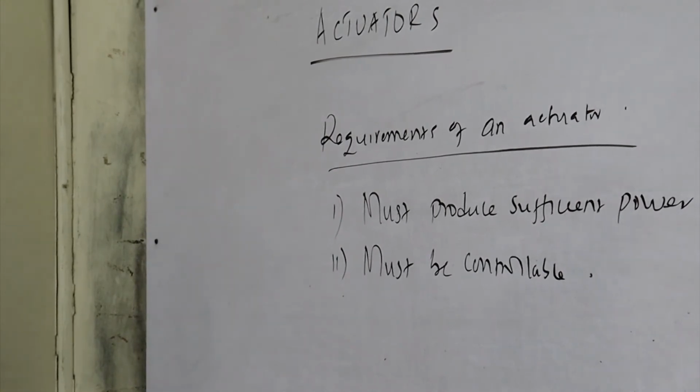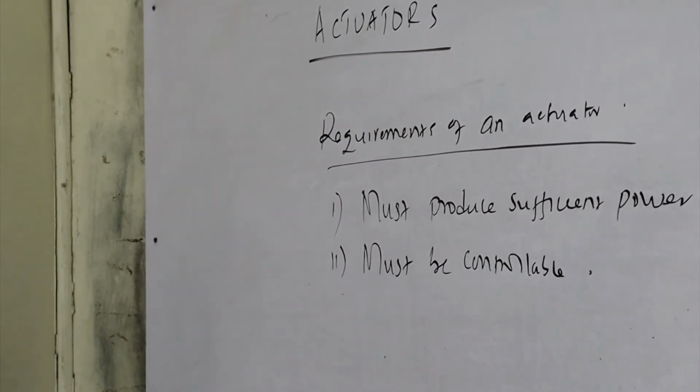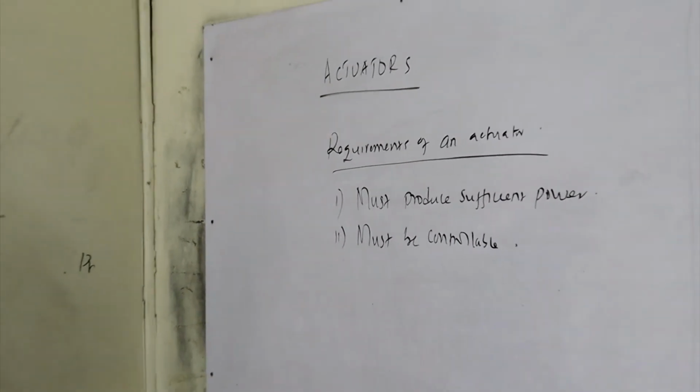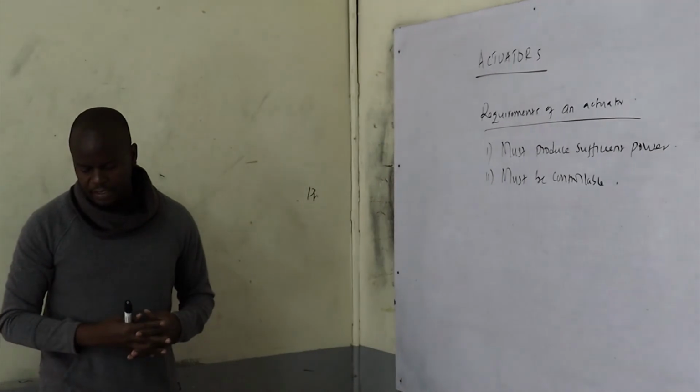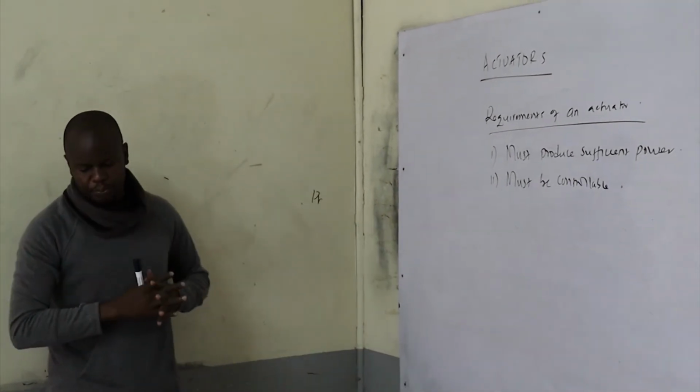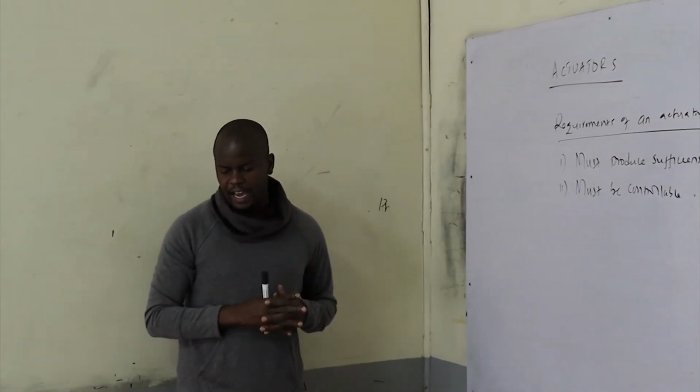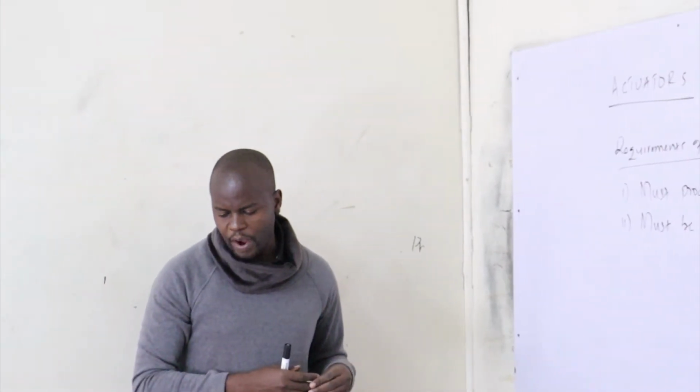And when you talk about the actuator, one form is simply a DC motor attached to a suitable gearbox, such that the angular velocity of the output is smaller than that of the input. If it is for an angular movement of a large mass, then the direction and speed of the motor has to be controlled. And this is always achieved by using a DC motor with a separate field winding.